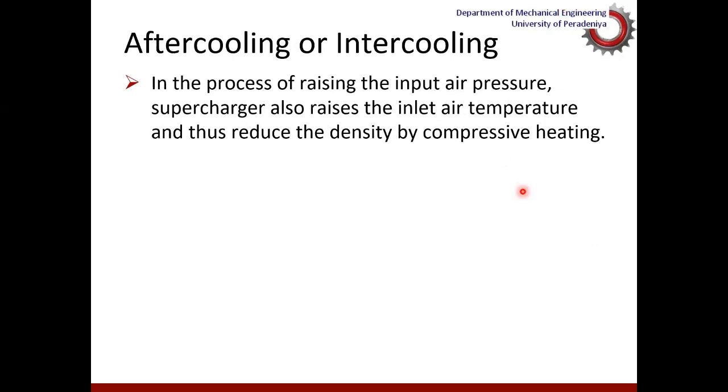Now, one observation we can make with turbocharging or supercharging is that when you boost the pressure, the temperature also increases. That leads to a reduced density of the incoming charge.